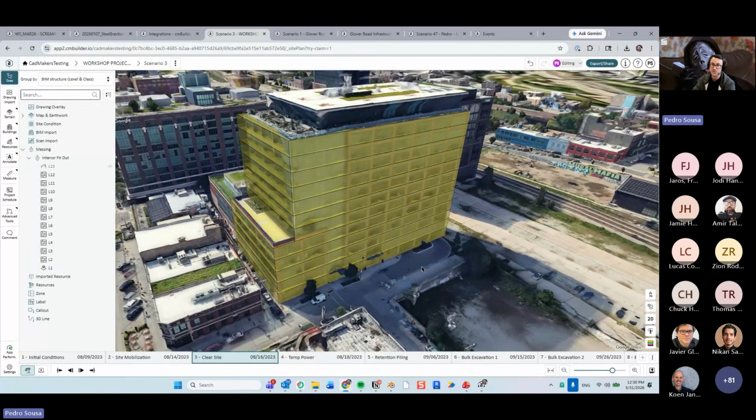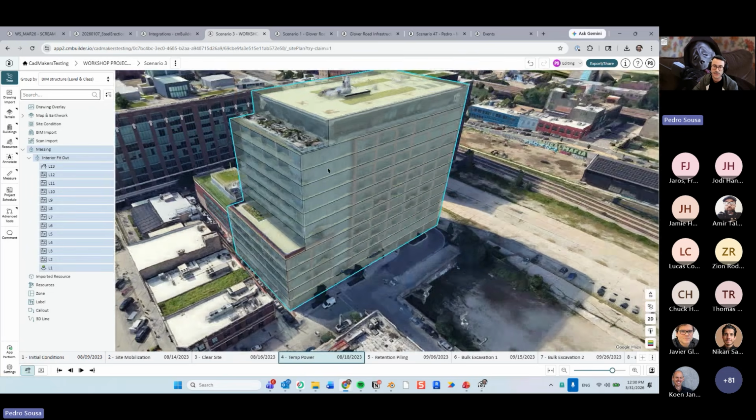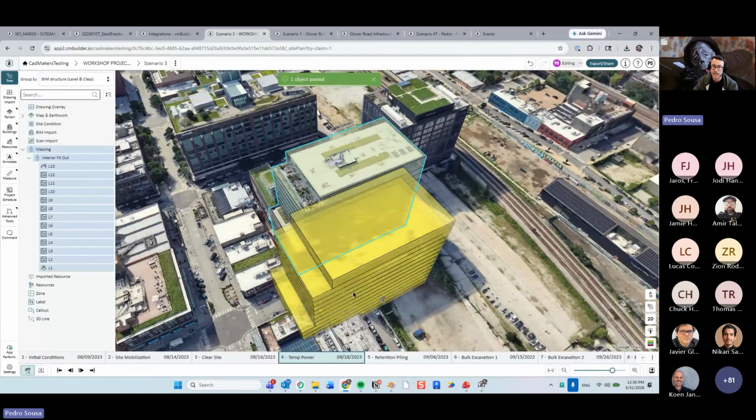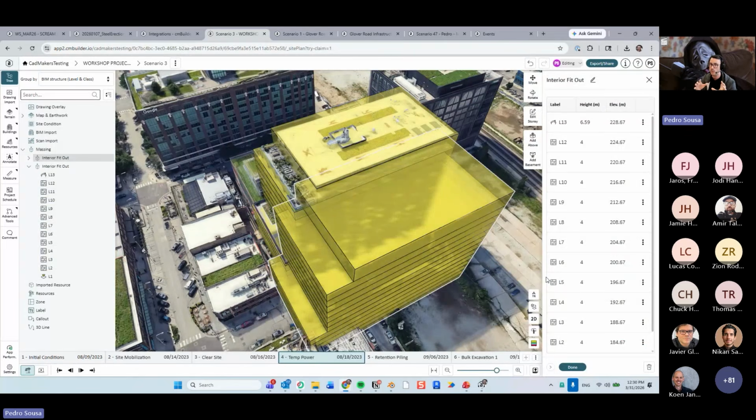So what you need to do is to duplicate this massing and create another massing with a whole different set of colors so you can hide and show them in different levels, right? So we're gonna click on this massing, then I'm gonna copy this guy, and I'm gonna paste it, just anywhere, right? We don't have yet a way of duplicating objects in the same location, but this is something that we're gonna build soon, the ability to duplicate elements in the same location instead of copy pasting and placing them wherever you want.